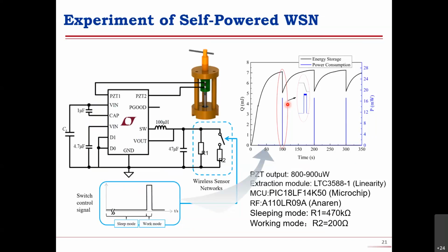We are also doing some experiments for the self-powered wireless sensor nodes, and we use the LTC3588 as a power management module, and we use two resistors to simulate the MCU and RF in their sleep mode and work mode by switching this switch on and off. According to our simulation, it is now totally self-powered with a 100-second sleeping mode and a 50-millisecond work mode.